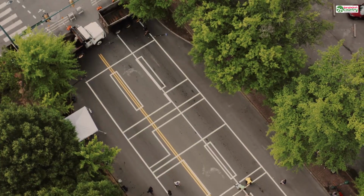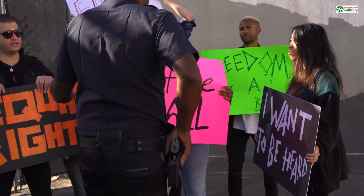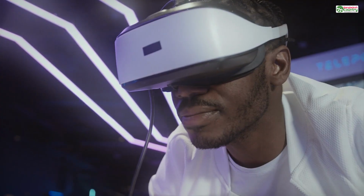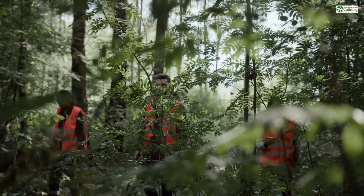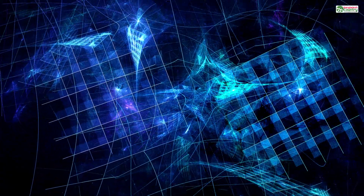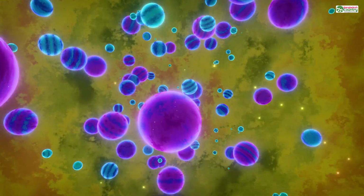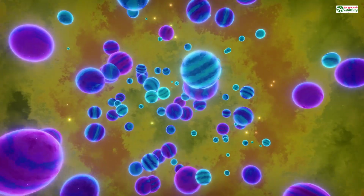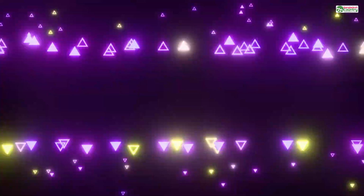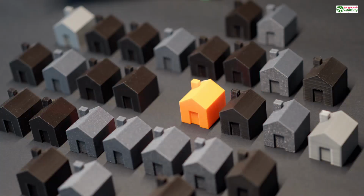Next up are the all-rounders, the daily drivers. This is where you find patterns like grid and triangles. Grid is essentially two sets of lines printed at 90 degrees to each other, creating a simple, effective mesh. It offers good strength in 2 dimensions, and is a fantastic default choice for many functional parts. Triangles take this a step further. We all know from basic geometry that the triangle is an incredibly strong and stable shape. An infill made of interlocking triangles provides great strength, and is another excellent go-to for general-purpose printing.